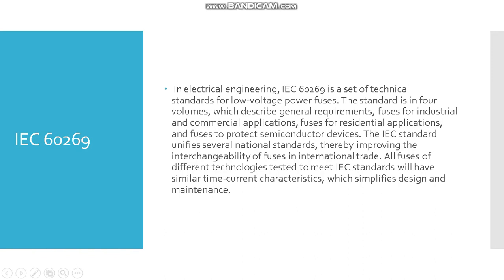Okay, so next is the IEC 60269 for the low voltage fuses. So here, this is a set of technical standards for low voltage power fuses. The standard is in 4 volumes, which describes the general requirements, fuses for industrial and commercial application, fuses for residential applications, and fuses to protect semiconductor devices.